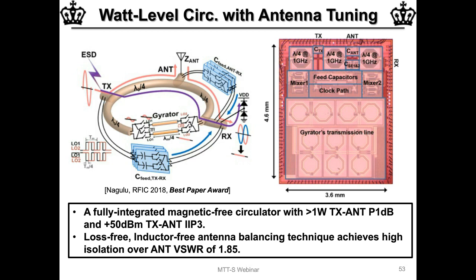the antenna. But ways to, even within the circulator, calibrate the phases accurately so that these spurs are inherently suppressed, I think, is an interesting topic, so that you don't have to add filtering and take the associated loss hit with that filtering. And so spur mitigation is something that we're looking at. Any clock circuit is going to have some spurs associated with the clock, but these are things that, in the circuits community, work has been done to calibrate those out.